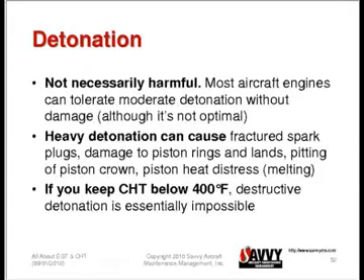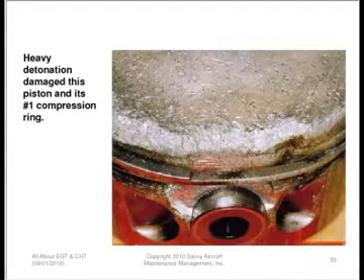If you keep CHTs below 400 degrees Fahrenheit, it's almost impossible for destructive detonation, heavy detonation, to occur. So by keeping close attention to CHTs and making sure they never get too hot, you will essentially eliminate the detonation risk. And if the CHT starts rising above 400, especially if it's rising rapidly, you have to take quite aggressive action to make sure that it doesn't continue to rise, because damage can occur.